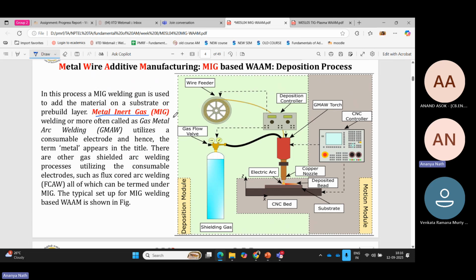Even if you forget what direct electrode, negative, positive are, just remember that if I have a negative and a positive pole, the negative pole will emit electrons because it has more electrons. That's why it's negative. And the positive pole will decay. So from the positive pole the deposited material will come, and from the negative pole only electrons will come, no material decay.